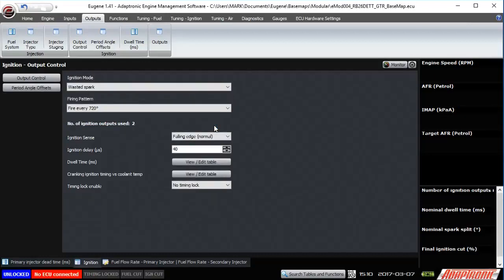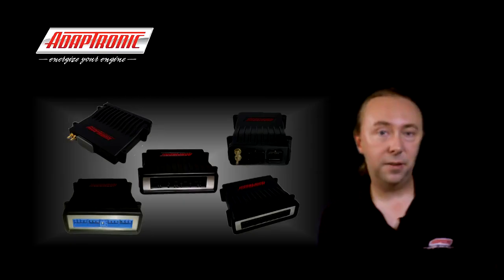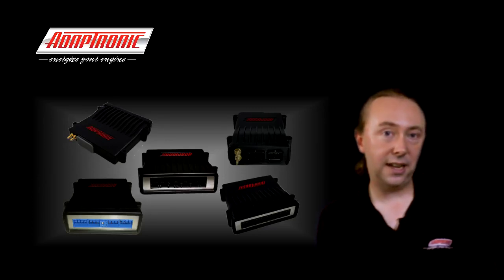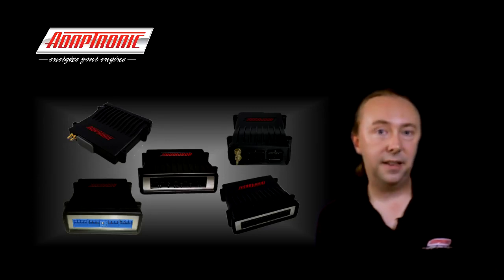Another mode is wasted spark. In this mode, we only have 1 ignition output for every 2 cylinders, and the firing pattern needs to be set to every 360 degrees. This works automatically for 4-cylinder, 6 cylinders, and 8-cylinder flat plane engines. For an 8-cylinder cross plane, you're going to have to change the ignition firing order so that ignition outputs 1 to 4 correspond to the 4 pairs of cylinders which fire at the same time.